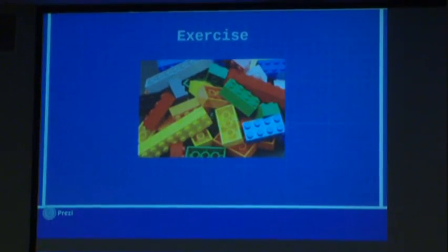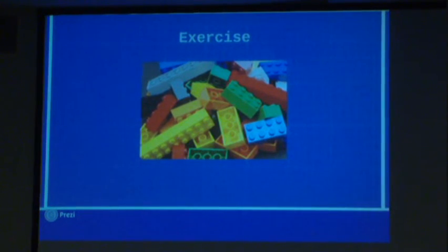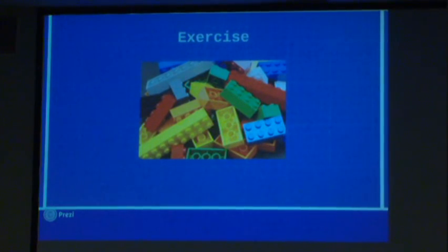I think we've got about 1 minute, which is not enough time for this exercise. If any of you want to practice these skills, which I'm sure you do, a basic concept would be take a 4 or 6 block Lego. You can do a 4 block Lego, simple. Okay? Take a 4 block Lego, draw it out as a print, and try and figure out what the tolerances would need to be for those Legos to snap together every time. Okay? Good? All right. If any of you do that and want me to check it, send it to me.